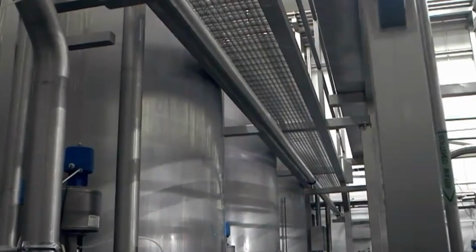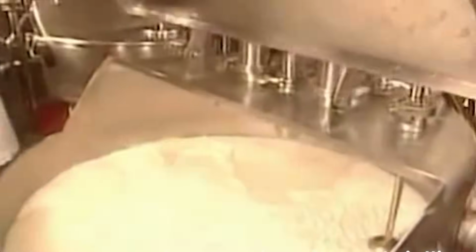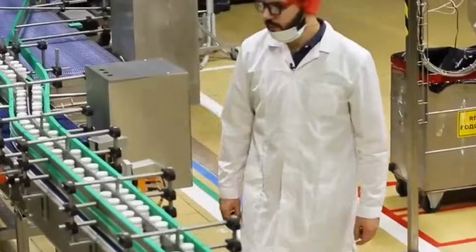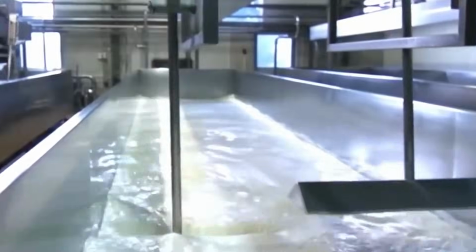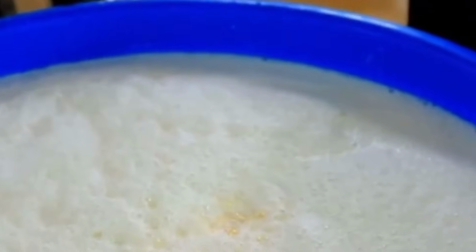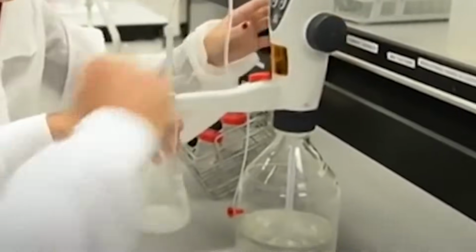Every unit, whether in cup, tub, or stick format, is passed through flow wrappers or form-fill seal machines. Packaging film is drawn over a forming collar, heat sealed along longitudinal and transverse axes, and printed with lot numbers and expiration dates using thermal inkjet systems. Products are checked on inline check weighers for mass accuracy, then metal detected using balanced coil systems capable of detecting contaminants down to 1.0 mm ferrous equivalents.